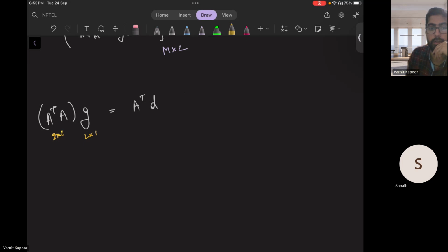All right. You can get the values of the gradients which you wanted from the least square method. So it doesn't matter how many phases you have. It's a 2 by 2 kind of system now. You can calculate this, invert it, and calculate what the gradient values are. So for every cell, you will solve the system once and get the gradient values. And then the G thus obtained would not satisfy any of these equations exactly; it will only satisfy the least square equations. That is the sense of the least square method.